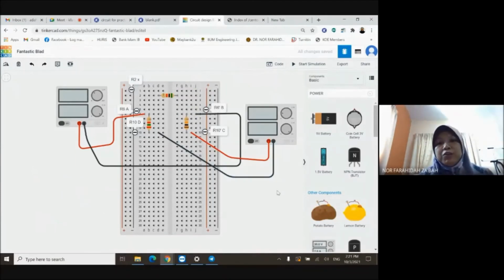Okay, so that's why we use a term called jumper. For a jumper, you basically put a wire and drag it to the particular node. So now I already define this node as node B. For jumpers, I like to maintain a different color than red and black. Basically you are connecting this row and defining this row as node B because of this connection.